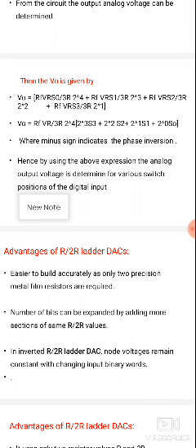V0 is equal to RF into VR S0 by 3R into 2 power 4, plus RF into VR S1 by 3R into 2 power 3, plus RF into VR S2, where VR is the reference voltage and S2 is switch 2.